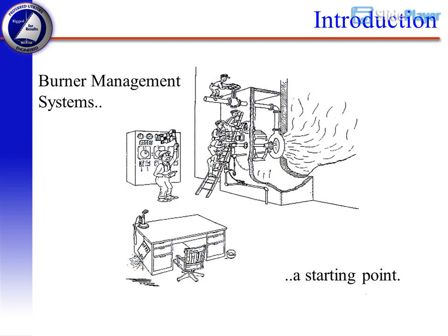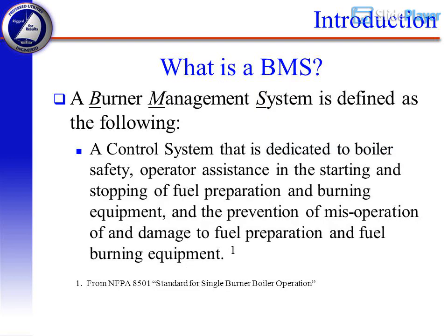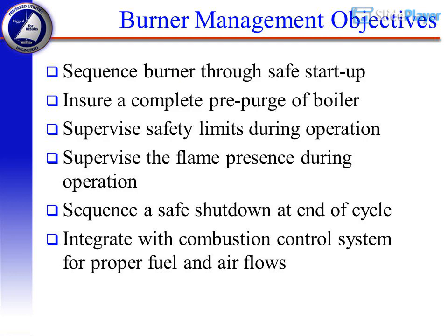Introduction. A starting point. What is a BMS? A burner management system is defined as the following. A control system that is dedicated to boiler safety, operator assistance in the starting and stopping of fuel preparation and burning equipment, and the prevention of misoperation of and damage to fuel preparation and fuel burning equipment. From NFPA 8501 Standard for Single Burner Boiler Operation.